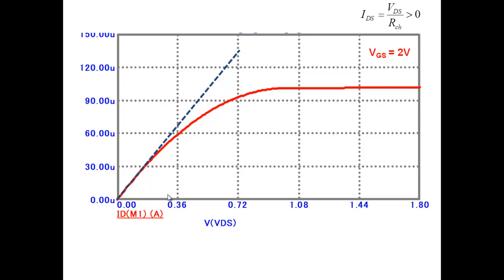So that's why the MOSFET is like a resistance in this region. It's like a resistance, but it's not a constant resistance. If it were a constant resistance, it would have followed this straight line. Therefore, it goes here and keeps on bending, bending indicating the resistance is higher and higher.